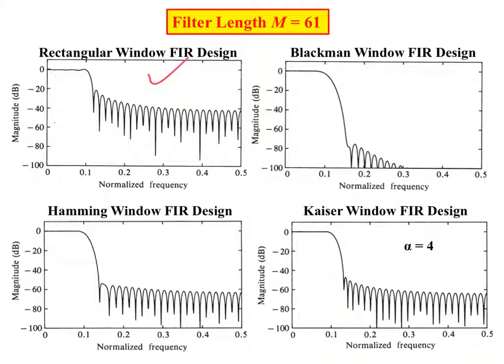In fact, they start with the same impulse sinc function kind of thing. And you can see what the trade-offs are here. These are all for the same length. So remember that the highest side lobe level will stay the same regardless of length. So here's the highest side lobe level here. Here's the highest side lobe level here.